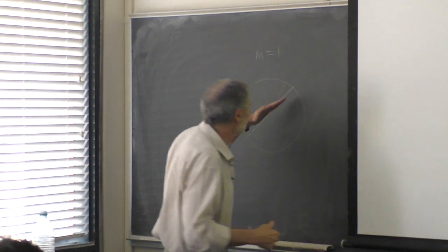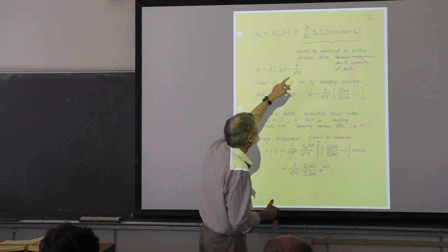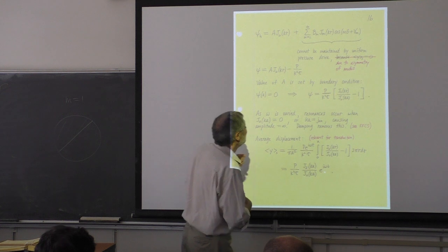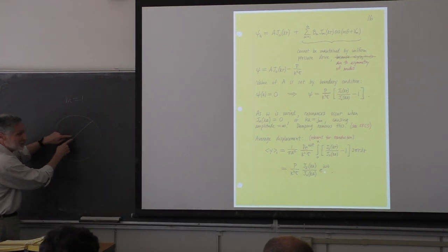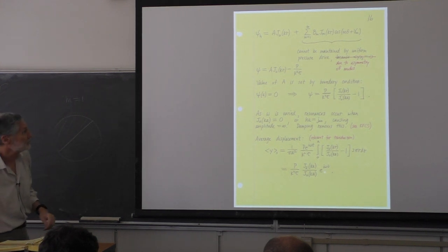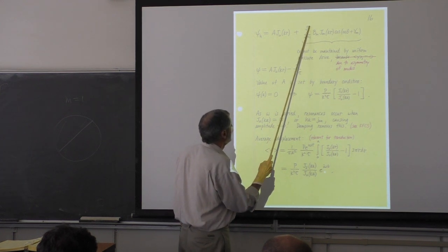And this nodal diameter can lie anywhere. And again, that's the reason for the gamma. The mode can have some amplitude. That's the reason for the B there. And then radially, there is a J1 Bessel function in the radial direction. And then, for the general homogeneous solution, we have to sum this up to infinity for all